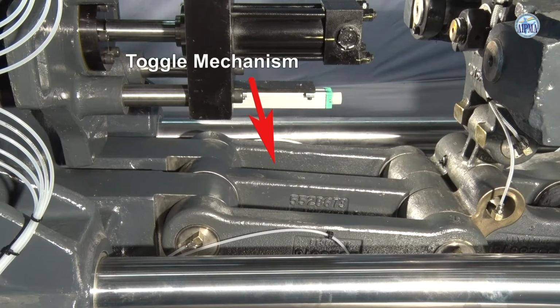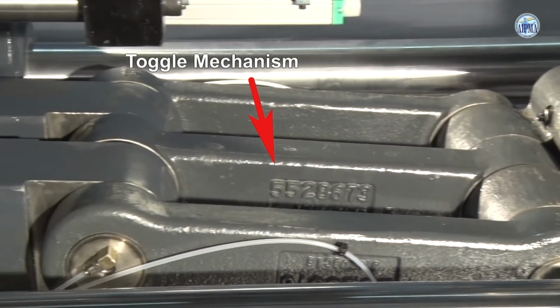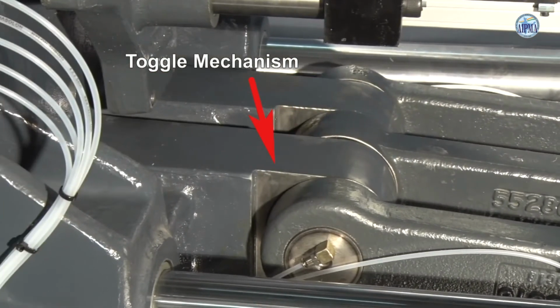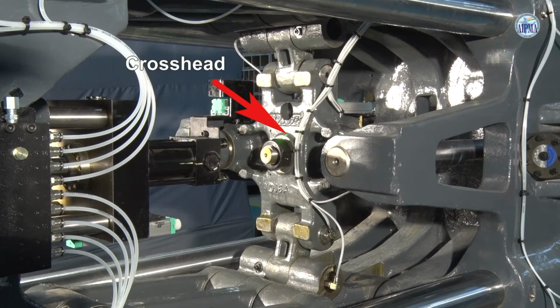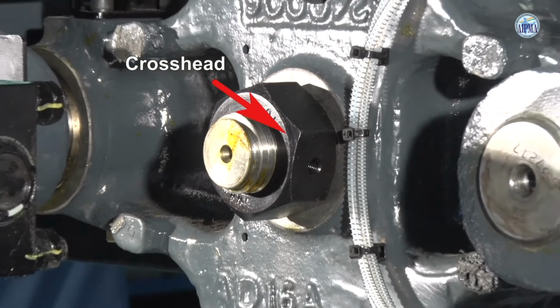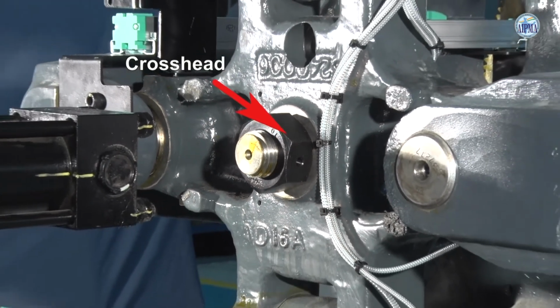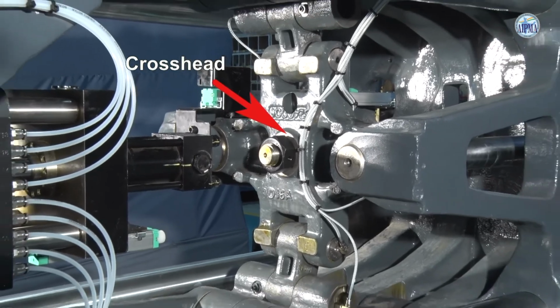Toggle mechanism. The toggle mechanism holds the moving platen and the die height adjust platen together. It is a mechanism for the movement of the moving platen and holding the mold in under stretch condition during tonnage. Crosshead. The crosshead is the mechanical link or coupling between the clamp cylinder and the toggle mechanism. At mold touch position, clamping force is applied on crosshead, which straightens the toggle links and maintain toggle straightness.